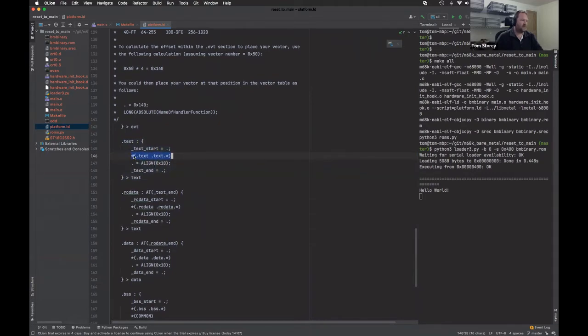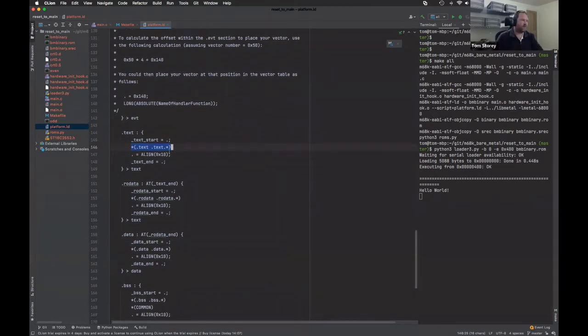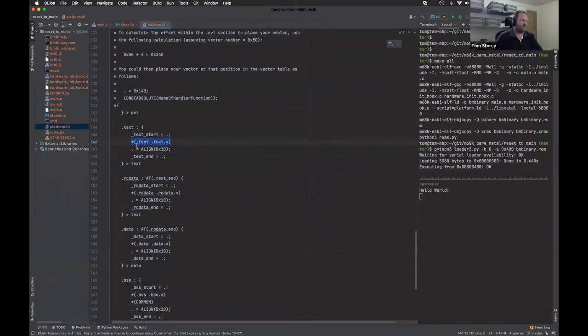So this is going to capture any time the compiler emits something into the .text or .text.something section, then the linker will find all of these, gather them all together, and place them into the .text section. And then the .text section is going to be placed into the text memory. So our main function, our little support function for printf, any other code that has been compiled, that's all going to end up going into the ROM.